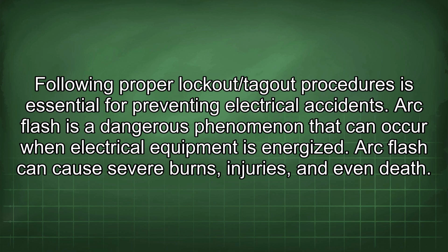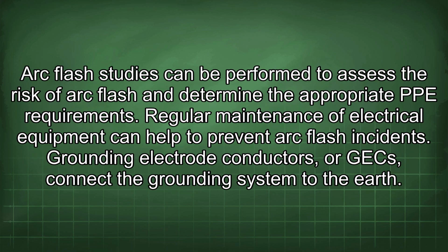Arc flash is a dangerous phenomenon that can occur when electrical equipment is energized. Arc flash can cause severe burns, injuries, and even death. Arc flash studies can be performed to assess the risk of arc flash and determine the appropriate PPE requirements. Regular maintenance of electrical equipment can help to prevent arc flash incidents.